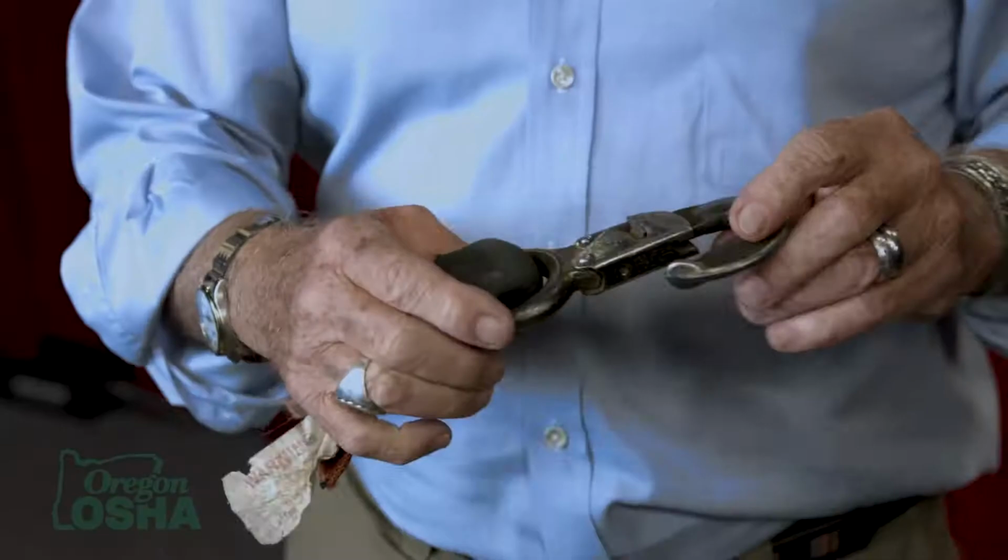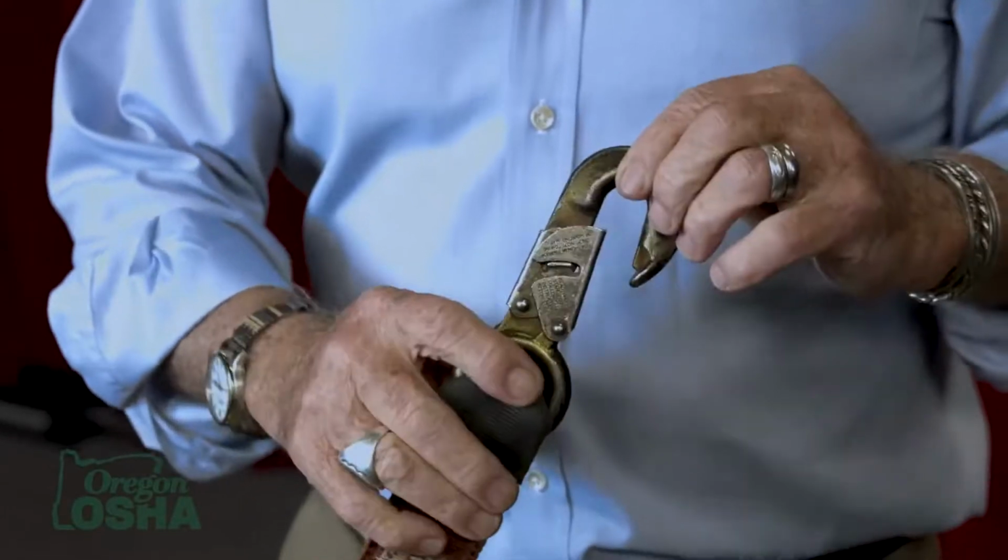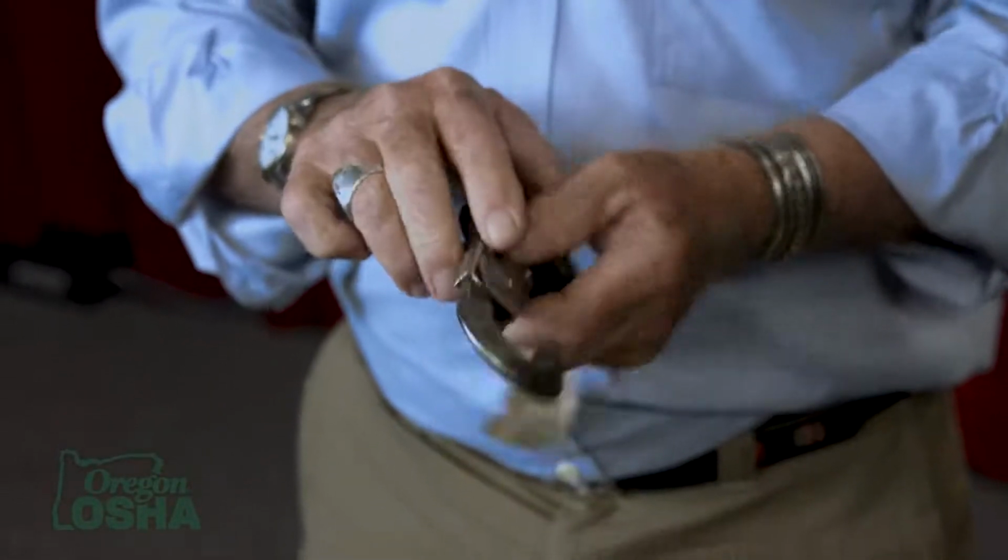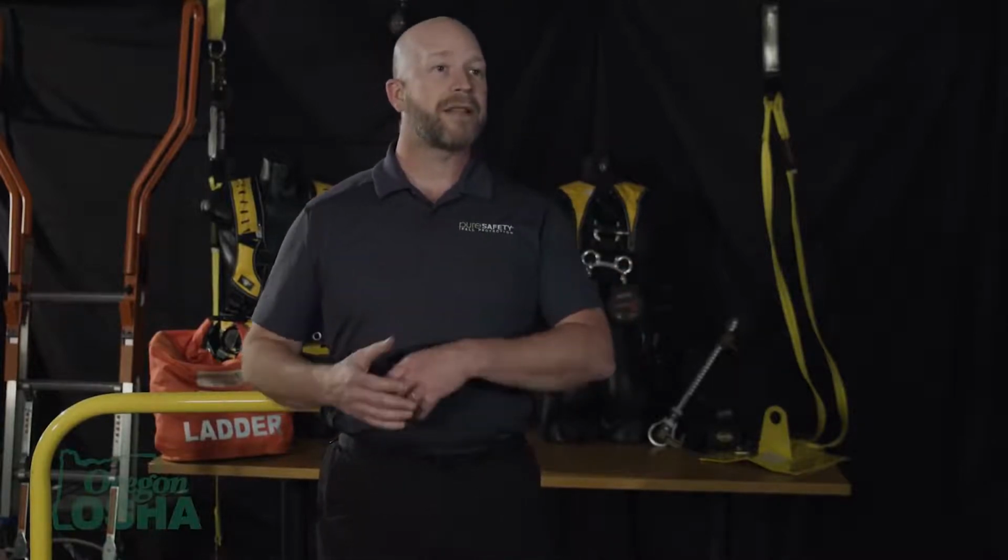So really the easiest way to define inspections is follow the manufacturer's instructions, but what we're looking for is anything that damages, hinders, or suspects its structural integrity or its functionality. If the snap hook doesn't close, the spring won't spring closed, there's signs of rust, not just a little surface rust, but actually corrosion, now the metal is suspect. Because it's got a little rust on it doesn't mean, oh my gosh, it's going to break right now, but it is no longer as strong as it needs to be when we talk about a dynamic load that is going to be applied should a worker actually fall. And there's no reason to ever say, well, I think I can save somebody's life. That is not an acceptable answer.